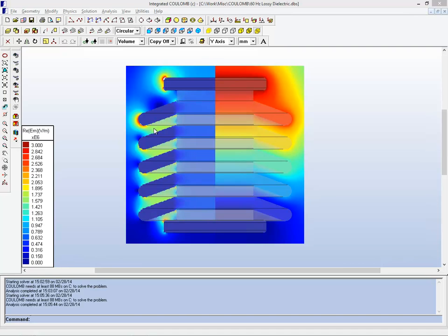So whether this is a good or a bad dielectric is going to depend largely on the combination of the permittivity, but especially the conductivity and the frequency. If we change to a different frequency, again referring to our formula, the imaginary part of the dielectric constant is the conductivity divided by the frequency, so we will of course change the balance between real and imaginary parts.